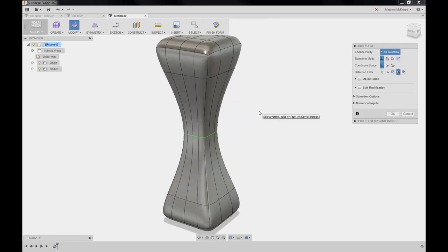Now, if you found that, I actually don't want to have its symmetry around the top and bottom, I want these edges around the top, but I don't necessarily want them around the bottom. In this instance and numerous instances, you can delete edges by group selecting them, and just simply hitting the delete key on your keyboard should delete them.